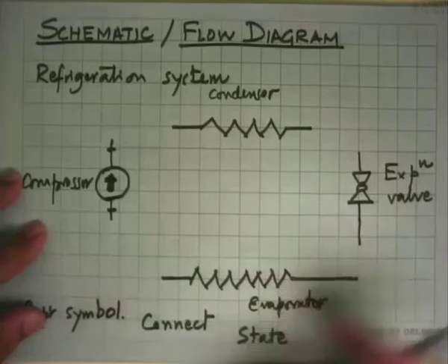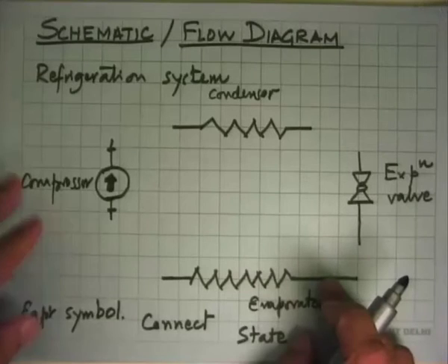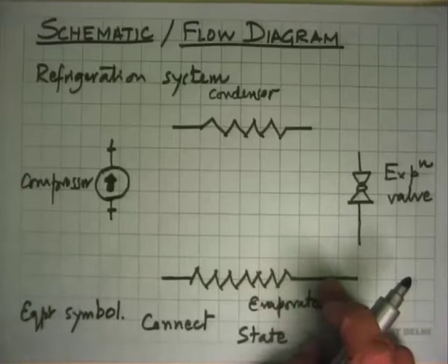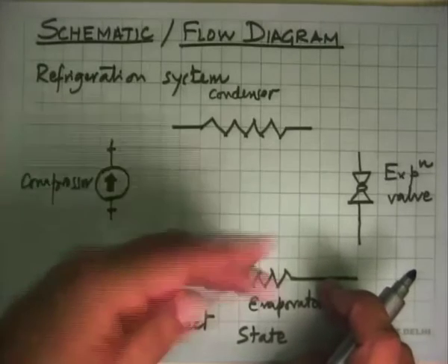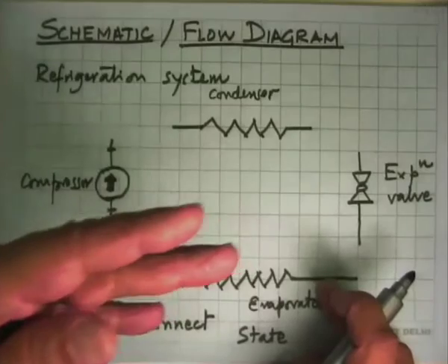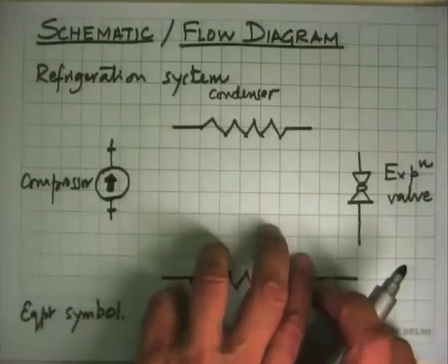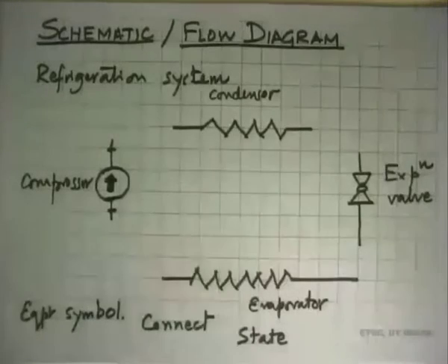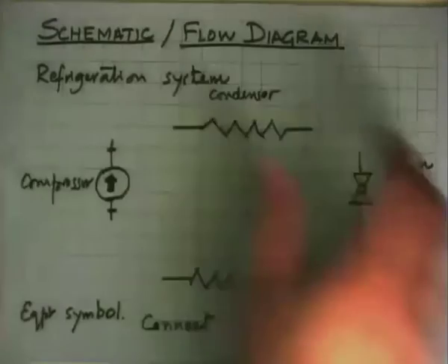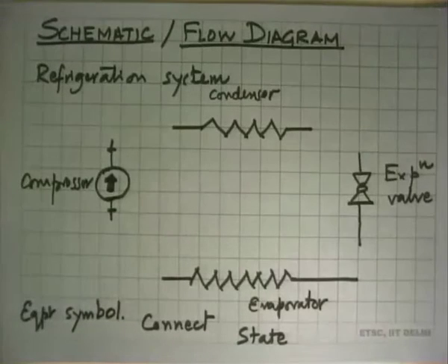And as the name suggests, what we had was a mixture at low temperature of vapor and liquid. This takes heat and the liquid evaporates to become vapor. In the process, it draws heat out from the surroundings and gets heated up. So we have four major equipment whose thermodynamics we know how we are going to analyze.